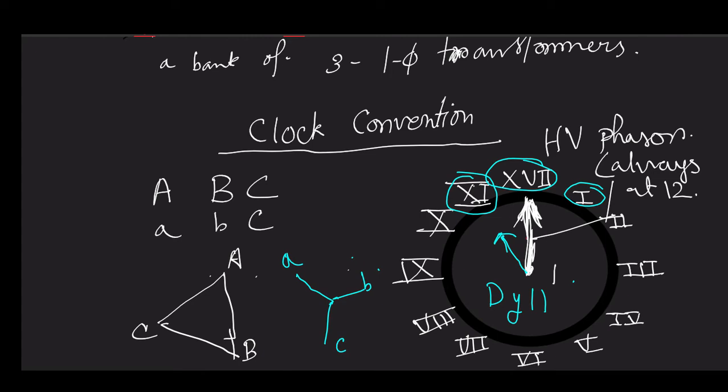So in short, what I was trying to tell, first of all, in a three-phase transformer, star winding is suitable for high line voltage applications, and delta winding is suitable for high line current applications. The advantage of a 4-wire connection is the availability of a neutral point, so you can easily find the phase voltage or easily connect any appliance that is suitable for single phase voltage level, readily without any additional arrangement.